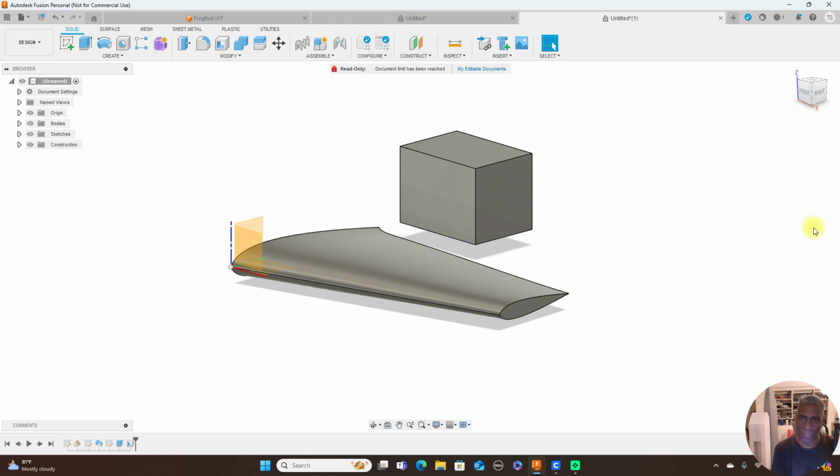And like I said, those are project, mirror, extrude, loft, sweep, split body, combine, shell. The forms that you'll use are the cylinder and square. In the sketch commands, you'll use a line, circle, and spline. And then you'll use your planes: the origin plane and the other two, a plane at an angle or an offset plane. So pretty much that's all I use when I model airplanes in Fusion 360.